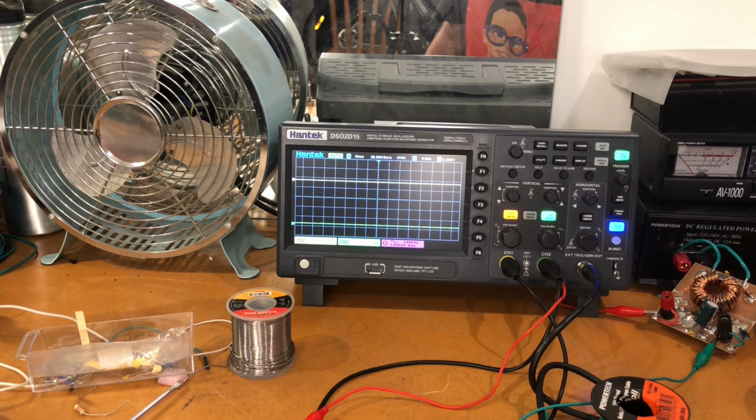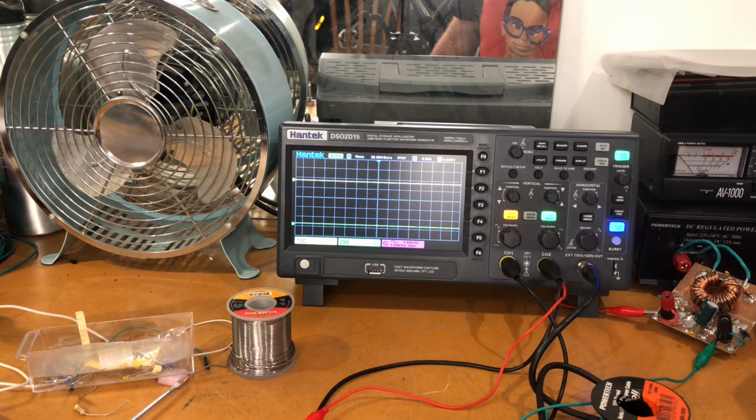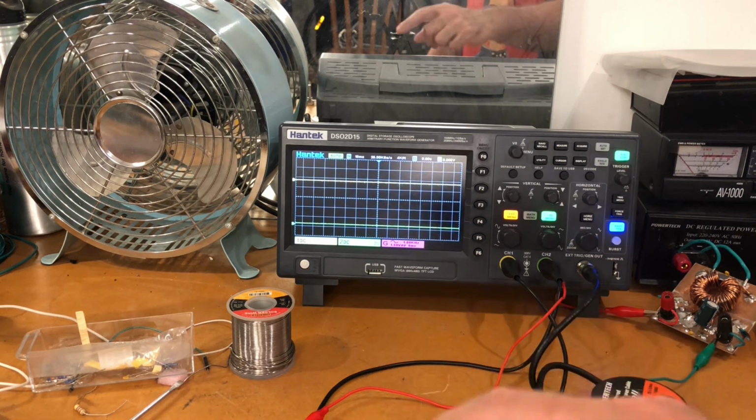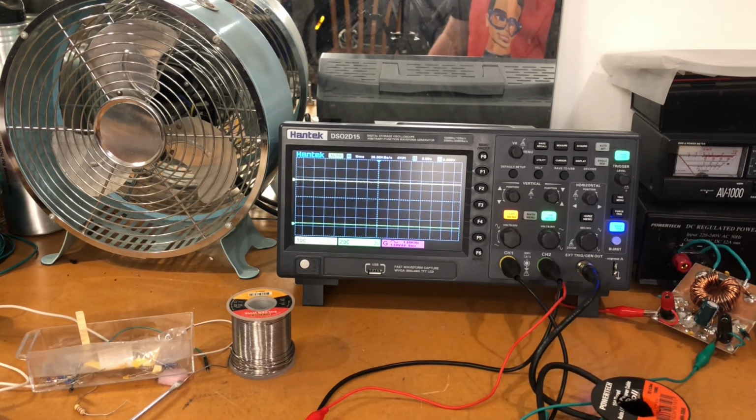Well, unsurprisingly, the circuit was designed for 9 volts, and I should have known better. But as you know, I'm rather flippant when it comes to electronics, and I'm constantly smoking components. So our BC547 has gone to the graveyard. I've put a 2N3053 here. I've put a series resistor in to lower the actual input.